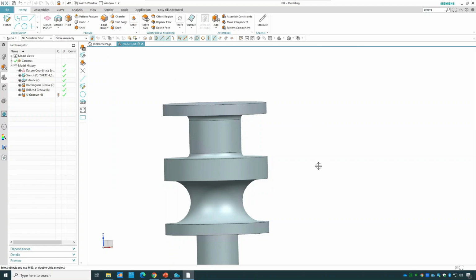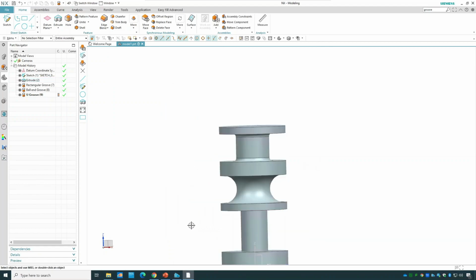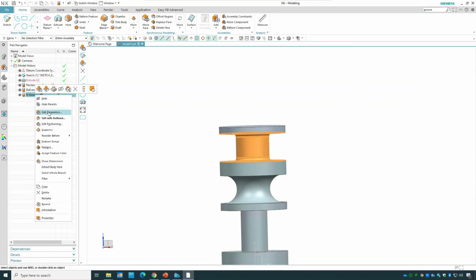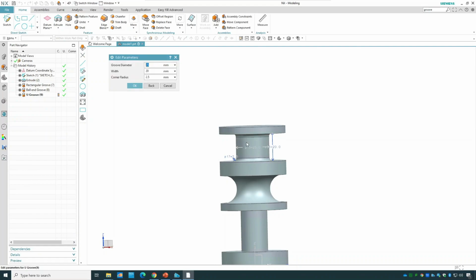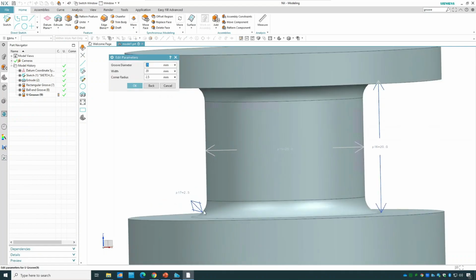So basically what you can see is the difference here. Here was basically like a rectangle goes and cuts it. Here was like a ball goes there and cuts it. Whereas here for a U is basically like a U goes there and cuts it. And the information that I put for the corner, 2.5, is here. So the corner of the U is basically controlled by that.